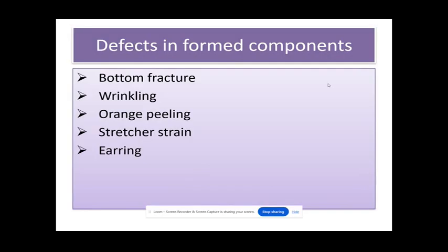Then we talk about defects formed in the deep drawing operation. One is bottom fracture, another one is wrinkling, another one is orange peel effect, next one is stretcher strain defect, and the last one is earring.